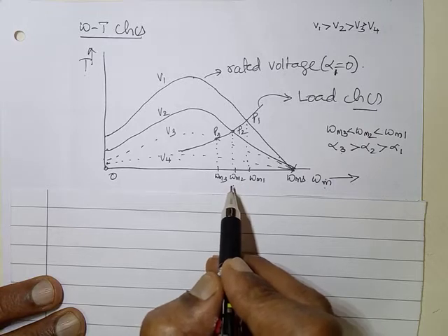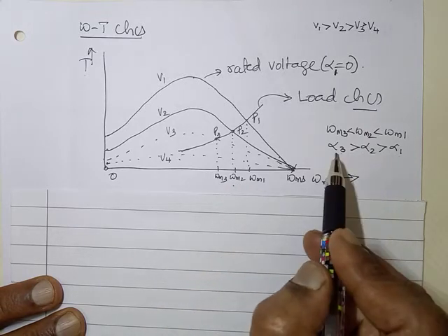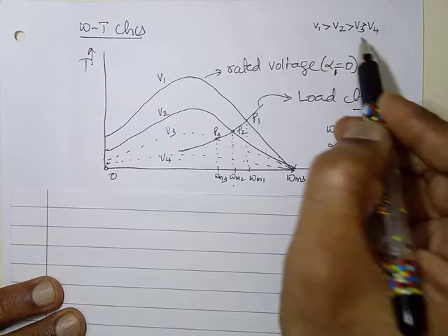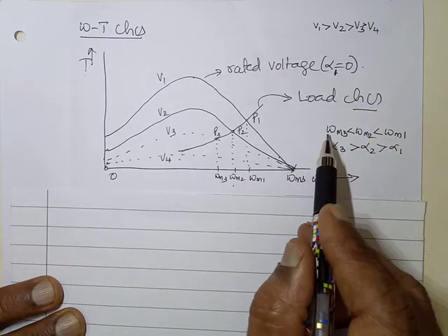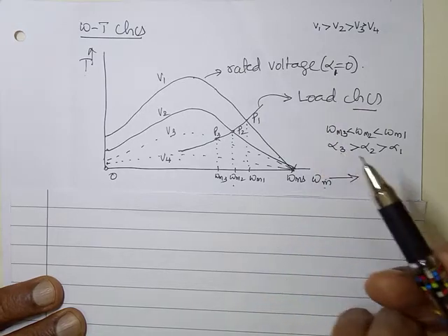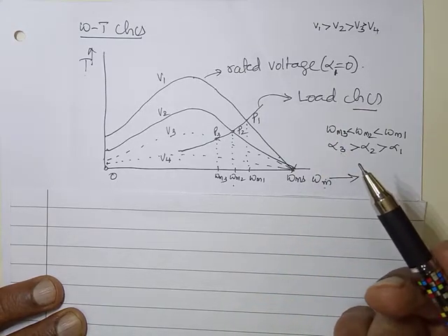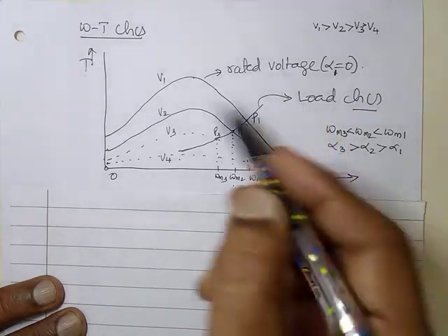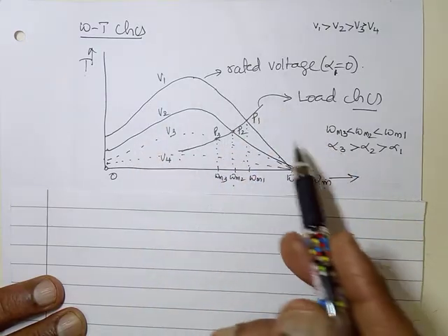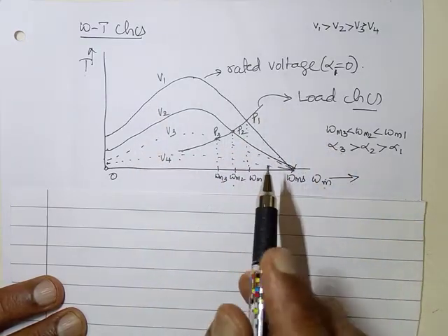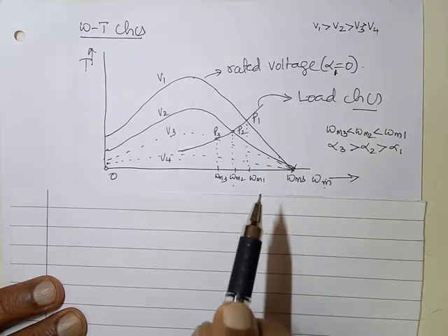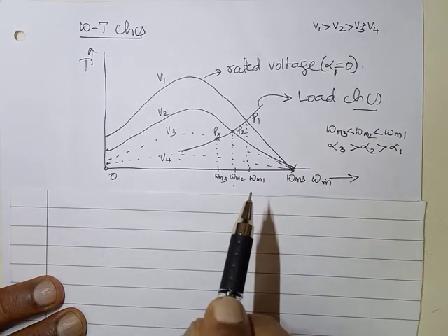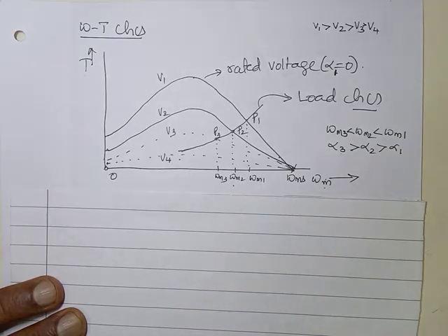That means by changing alpha, hence changing the voltage, I can change the speed. That's what we mean by control. Am I right? Good. This is the whole thing that goes on in the three-phase voltage regulator based three-phase induction motor control. There is something very interesting here.